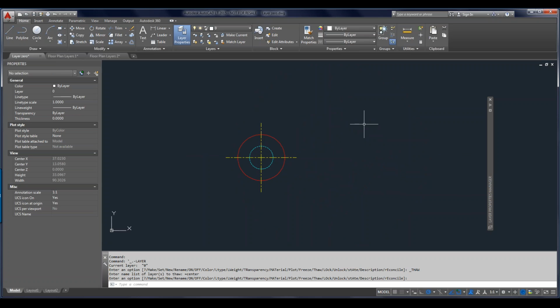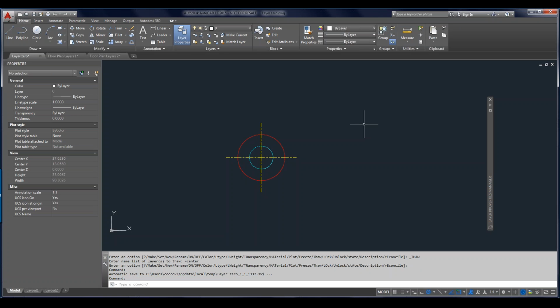There was actually another question about this that just came in before we move on. If a layer is frozen and you decide to move the circles, will the frozen layer move with the circles? No, AutoCAD ignores it. The same thing pretty much works with the off command, but you still need to be careful. If you use something like select all, you're going to move the stuff. AutoCAD still knows it's there. But freezing it, it's going to ignore it. So you do need to be aware of what's going on in your drawing.